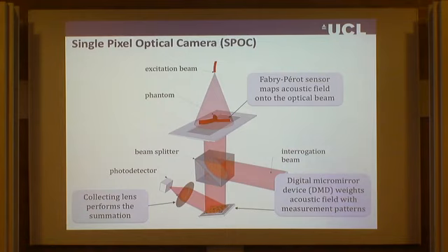Like white noise? Yeah, so it is like 0 and 1. So you look at the pixel or you don't, basically. But you are right. So the original idea is to have a random vector that you take a scalar product with. So this is what this hardware does. So this is just the digital world. You can get micro mirrors that operate at gray levels, but they are much more complicated and expensive. I think Fraunhofer at some point was working on something like that. So the bottom line is this is a scalar product with Bernoulli vectors.